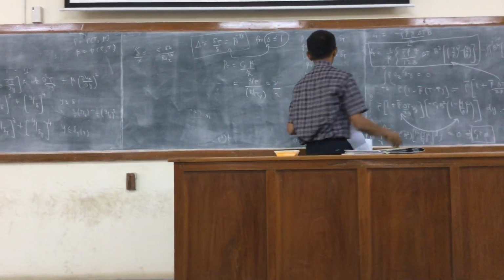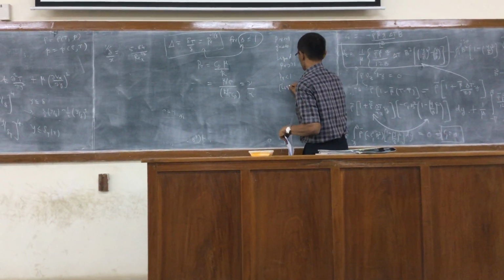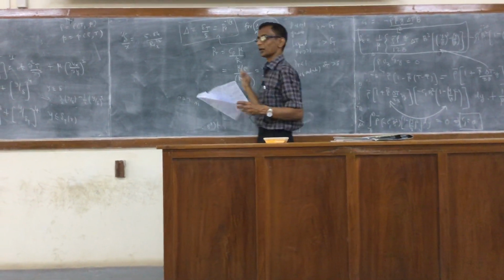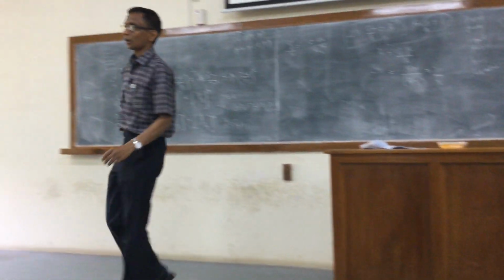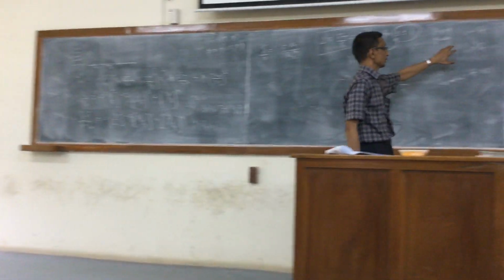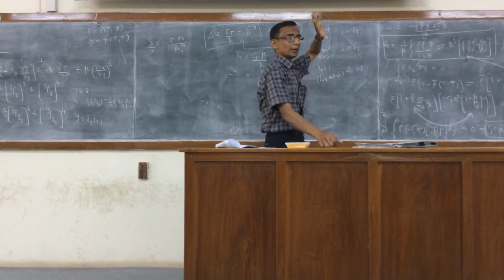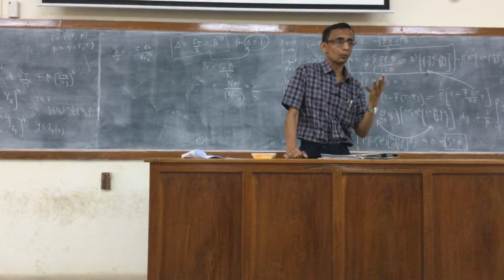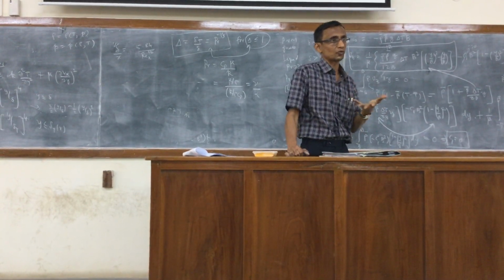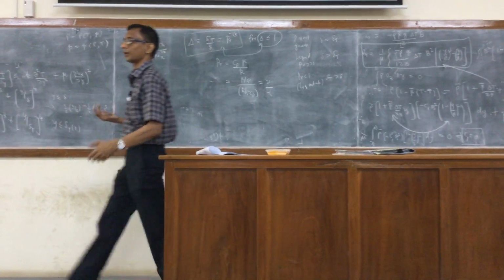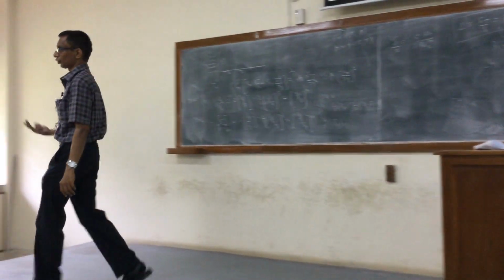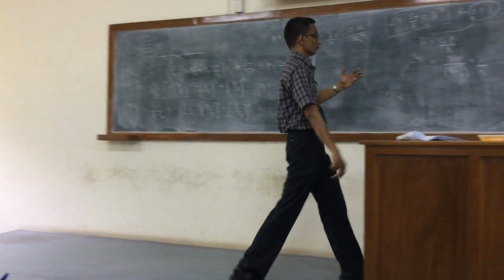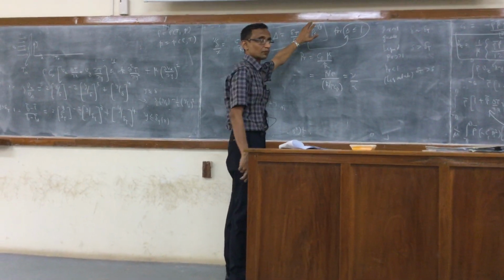So this is for liquid metal. Let's take this for liquids where the hydrodynamic boundary layer is greater than the thermal boundary layer. We have seen that the kinematic viscosity actually appears in the vorticity equation, which is often referred to as the momentum diffusivity. We have seen that it also represents the vorticity diffusivity. In the vorticity equation, it appears as a diffusion term, multiplying the Laplacian of the vorticity.